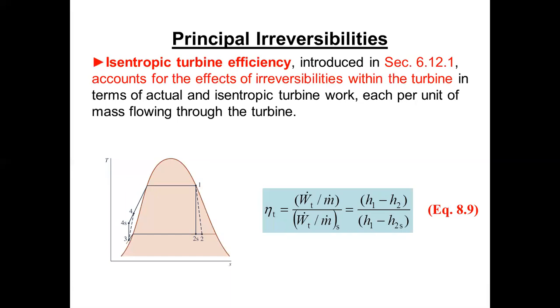The other thing to note is that in the real turbine, the blades are happier at 2 than they are at 2s because there's less moisture. The quality is higher at 2 than 2s, indicating that there's less moisture, and that we're not beating the blades up as much as they rotate around the wet sections of the turbine.